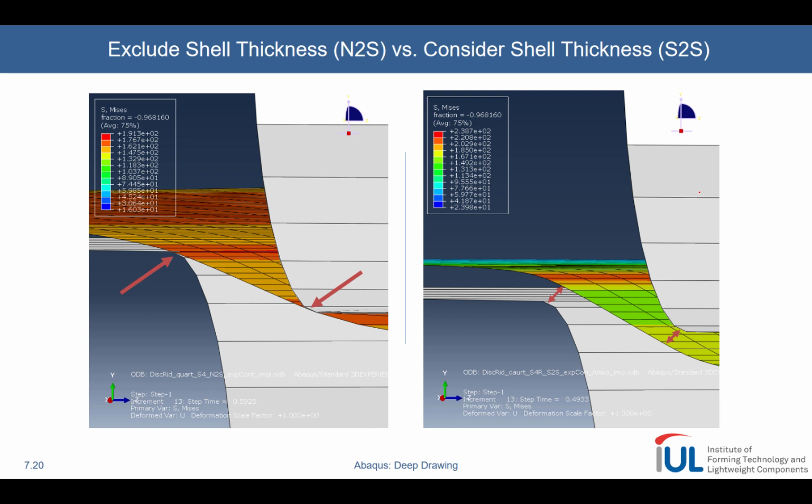And if we look at the results, you can already get a pretty good feeling why this really matters. On the left, only when the actual two-dimensional object, the center of your sheet, in both cases I've defined the mid surface to be the reference for the sheet, you see that the overall deformation of your sheet looks vastly different to the one on the right, where you have a much higher curvature.